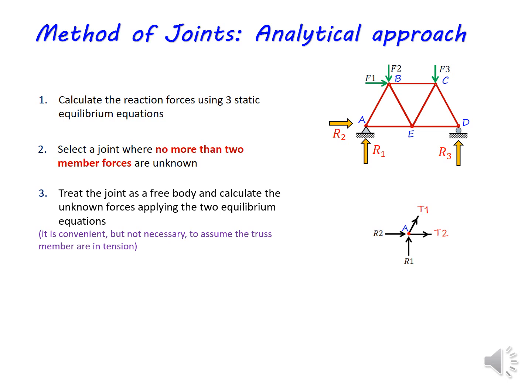Now you may notice that I have marked those member forces as tensile forces. It is not necessary to assume all the truss members are in tension, but to make the calculation simpler, we mark the member forces as tensile forces and proceed with the calculation.